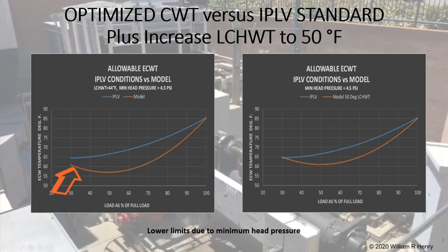Just in case you are wondering, the upward lift of the red curve at the beginning or left side is due to the manufacturer's minimum refrigerant head pressure requirement, plus a safety factor.